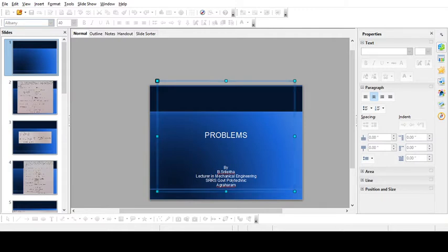Next, stress in the bar: sigma is equal to load by area. The induced stress is nothing but force by area, that is 15 into 10 to the power of 3 by 25 pi. So you will get a value of 190.98 Newton per mm square.